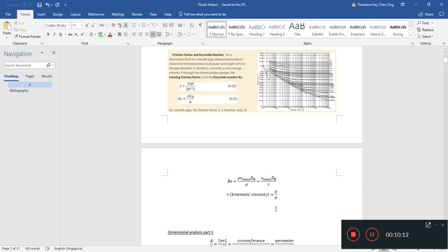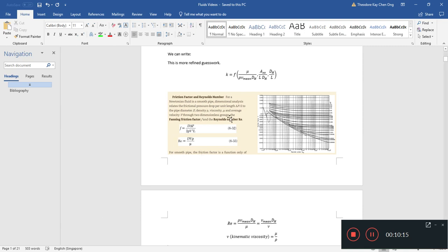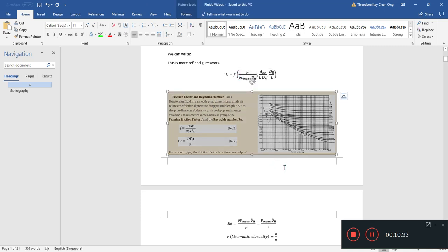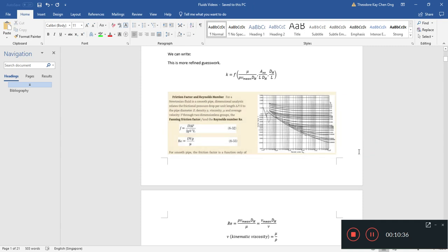That's all. Okay. So you see that this Reynolds number is very important, and that is why I chose this dH. Well, because it's already been experimented on, and it's found that this combination of parameters in particular has been especially important, and you don't see really much else. Now, take a look at this K value, and take a look at this thing called the Fanning's friction factor. What do we see in there?